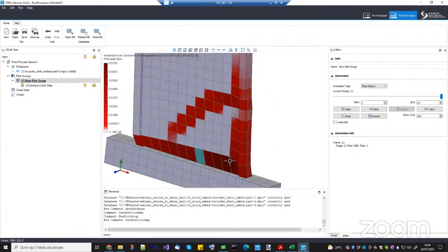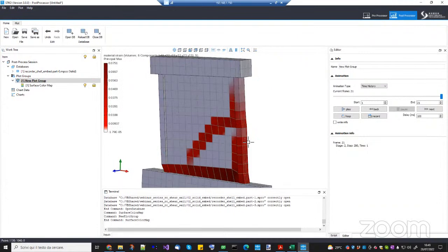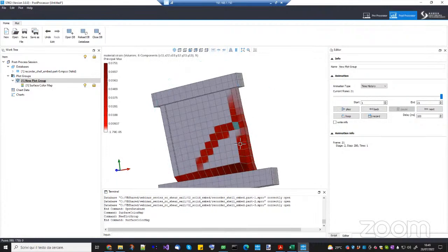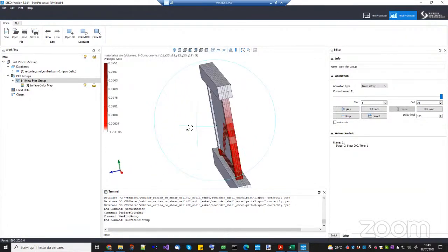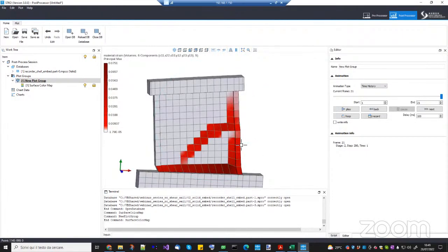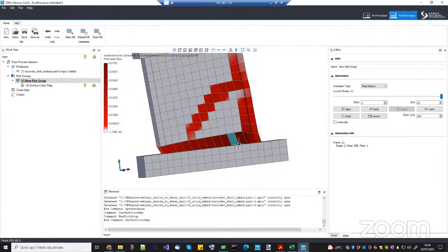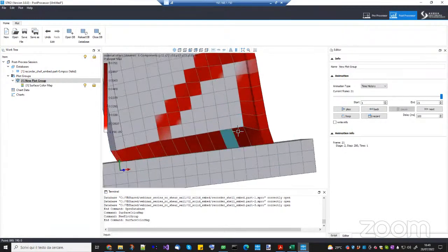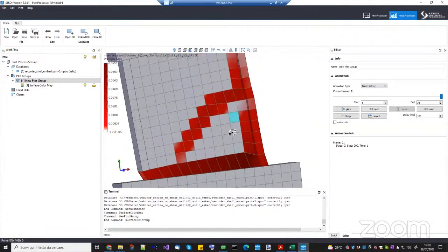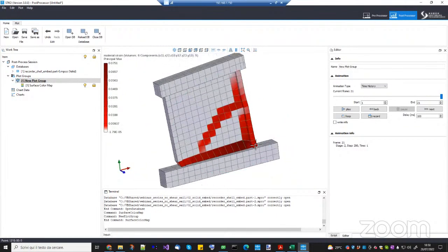But what you can see here is that the column, which was the same thing that was happening in the previous model where the beam was modeled as a beam element, basically everything is damaged. You don't see cracks here. So probably this kind of behavior was due to the strain penetration, which is not modeled in this case, especially here. The rebars which are embedded in the damaging model are still completely attached to the concrete. Well, actually the concrete there is gone. So probably using the standard embed is fine, but not so much in this kind of case.